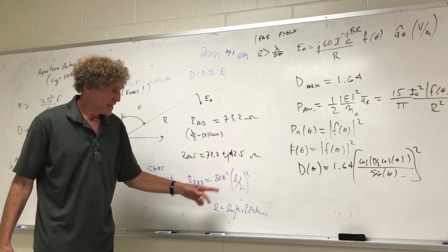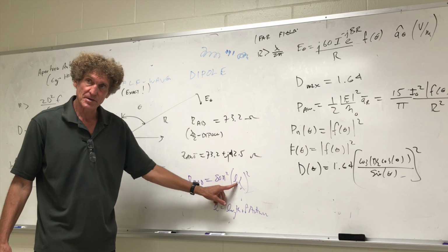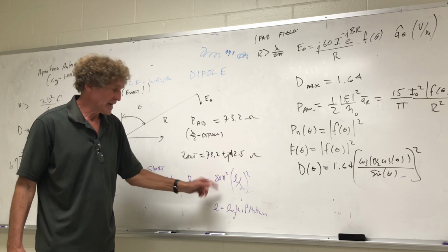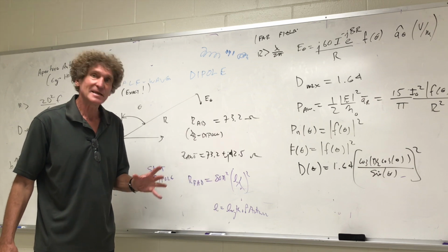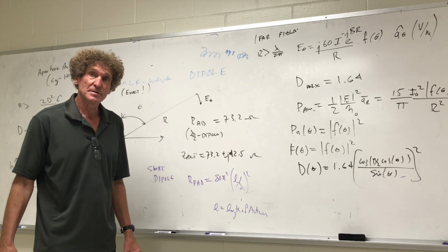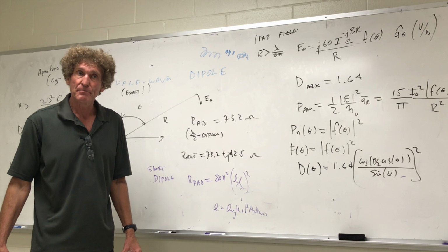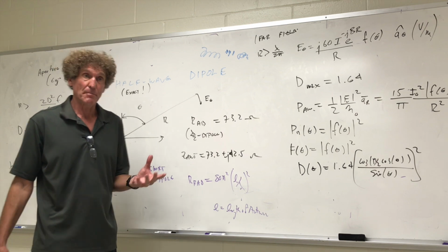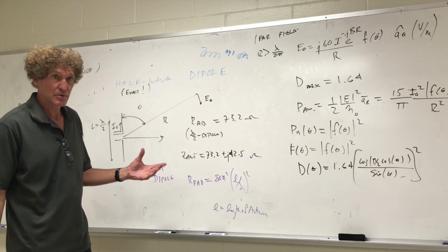Just think about it. If L is a tenth of a wavelength divided by a wavelength, we have 1 over 10, right? Squared, 1 over 100. 80 over 100 is 0.8. 0.8 times pi squared, it's less than 10, right? Less than 10 ohms. That's horrible. I mean, your copper losses now may be significant. They may take a lot of that power instead of radiating. By the way, you have to drive a lot of current to get any appreciable power out of it.